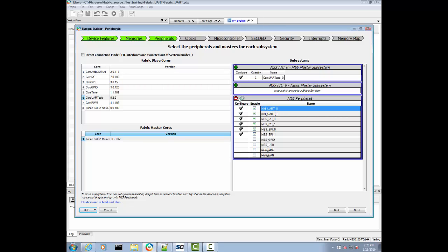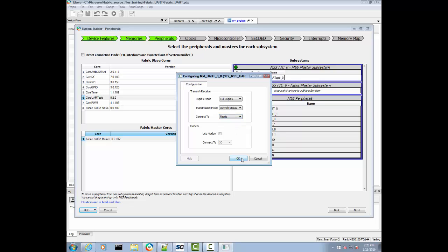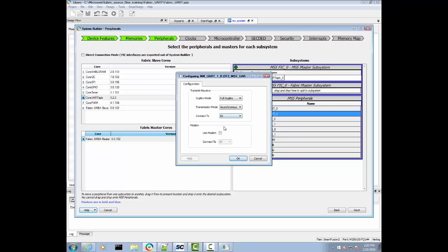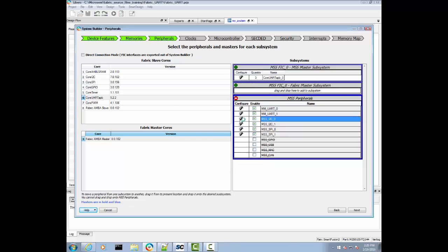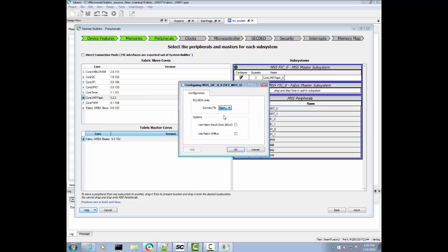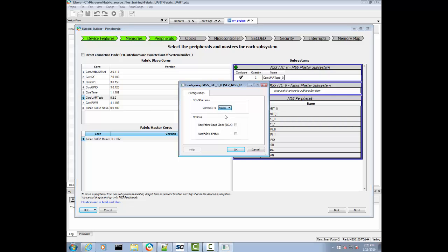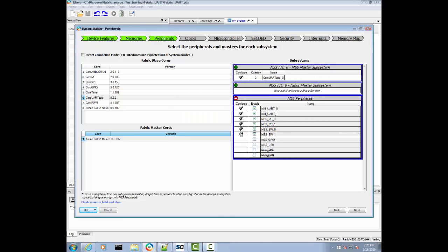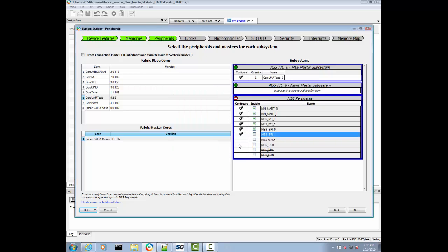Got an error message. That was indicating an error. The reason for the error is that some things are specific to the particular package that we're using, where some of the connections that have dedicated IOs aren't available, and I have to connect it to the fabric instead. This is one of the smaller packages, the 144 package. And by going to that small package, they've disabled some of the IO paths. So we'll connect these into the fabric instead. Now the problem's gone.